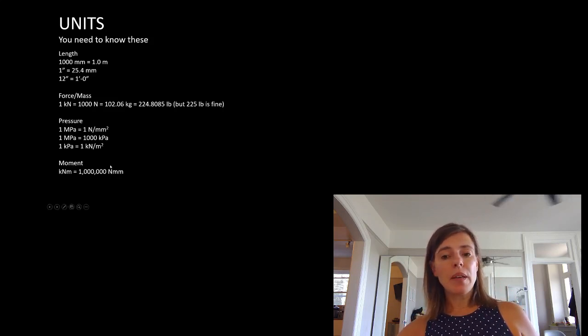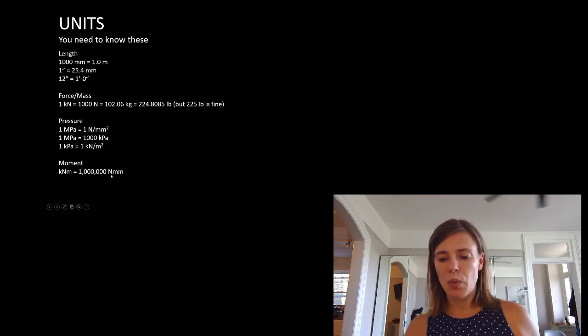Moment. Moment is something some people have never heard of until we've started these lectures. But moment has the set of units kilonewton meters. Sometimes we have to work in things in kilonewton meters, and sometimes we have to work in things in Newton millimeters. The difference between those is a million. So 1 kilonewton meter is 1 million Newton millimeters. So we're going to have to convert back and forth between those sometimes.